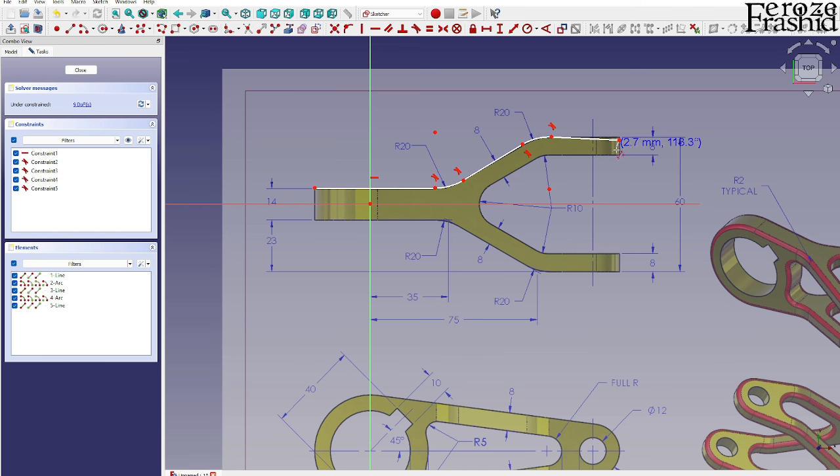I am using polyline to draw these boundaries, and polyline gives the chance to go through straight lines and arcs by pressing M repeatedly on the keyboard. M stands for modes, I believe. And see where it says this line is going straight because it's tangential to that arc.